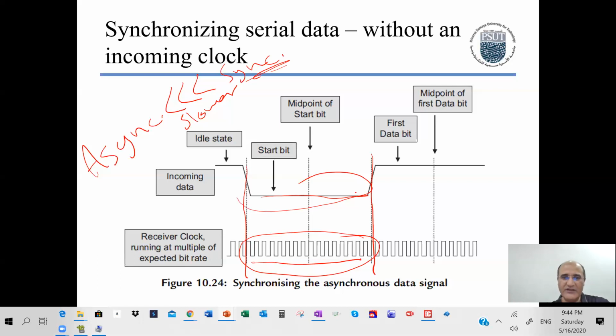So when the receiver detects a start bit, it counts 20 times, then it knows the first bit is going to come. It takes a sample after the 3rd clock, a sample after the 7th clock, a sample after the 15th clock, and averages the samples or looks at the majority. If they were high, it considers the bit received as high. If they were low, it considers it low.